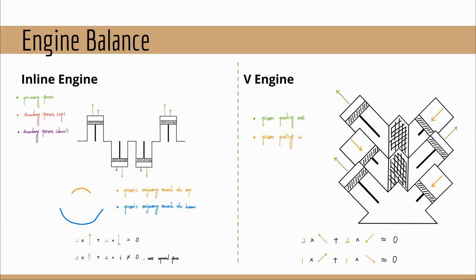As we can see, the primary forces cancel out. However, the secondary forces don't cancel out to zero, resulting in a net secondary force within the system, causing imbalance through vibration.